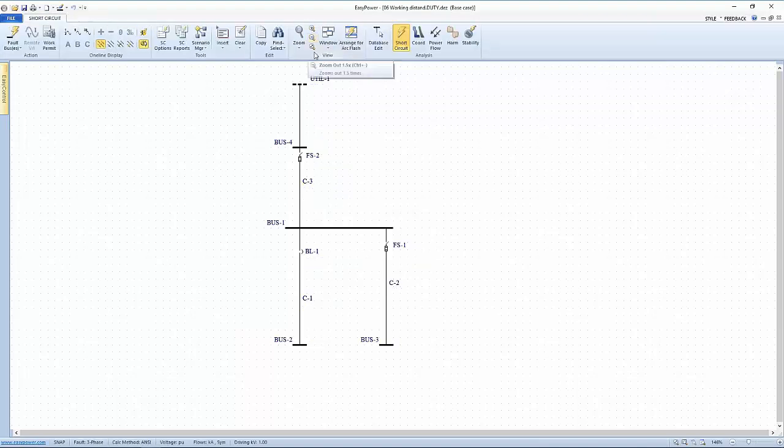I'm going to go ahead and enter short circuit focus, fault all the buses, and look at my incident energy. Actually, I'm looking at equipment duty here. Let's look at incident energy, and I see on a couple of buses that I have elevated energy, and it looks like I've saved the example already with my default set at 14 inches.